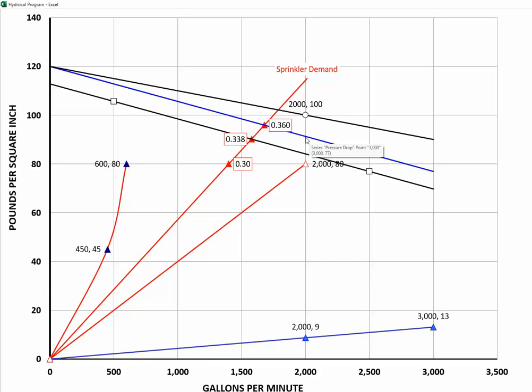And from this water supply line, we give 500 gallons to the fire department. We take this point, 3,000, and subtract 500. So at 2,500, we draw a line. And we do the same thing over here at 1,000 GPM and 77 PSI. We subtract 500 GPM. So that gives us 500 GPM at 77, and we connect the two lines. And this represents the water supply available after the fire department arrives.